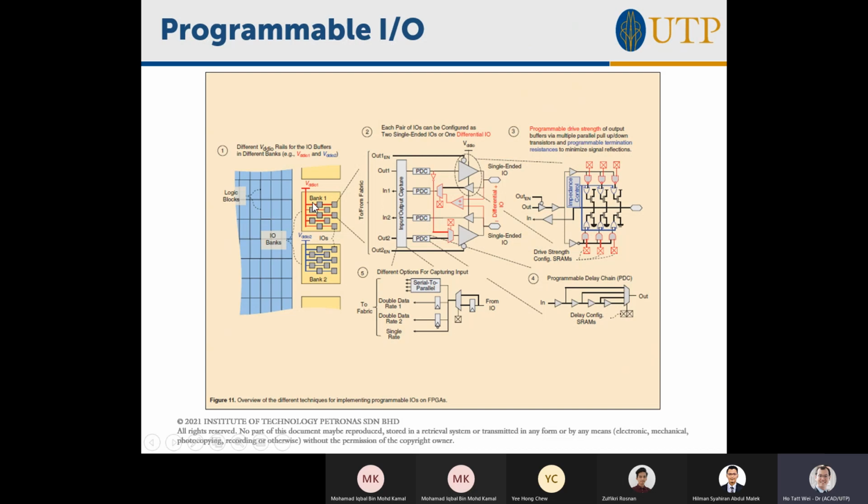Now, I think you know that digital logic has multiple logic families, right? You have 5 volt TTL, 3.3 volt CMOS, 2.5 volt CMOS, 1.8 volt CMOS, 1.1 volt CMOS, and something called LVDS, low voltage differential signaling, which is on the order of 100 to 200 millivolts. You know that, right? The different types of digital logic standards, right?